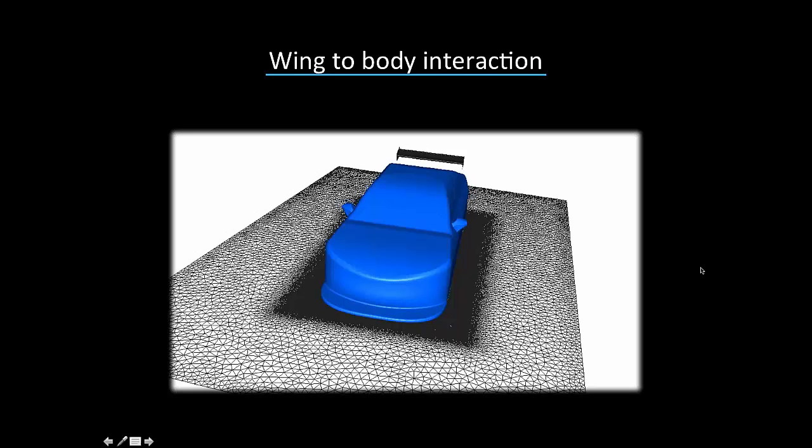This is one of the preliminary CFD models I used on the car. So you can see it's very easy geometry there. It was really quick to mesh. It was not very intensive for computing time and things like that. So we're able to just take a standard supercar wing on the back there. That's actually just a VE Supercar wing, and I was able to move it up and down and check different angles and see where we got the best wing to body interaction on the car, where they would complement each other rather than just moving it right out of the way.